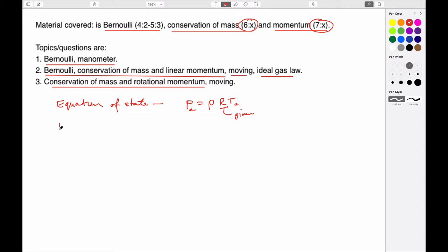The manometer equations: you know the rules that are used are that if you go up, you subtract pressures. If you go down, you add pressures. The pressures are given relative to a reference pressure plus the unit weight of the fluid multiplied by a change in height.